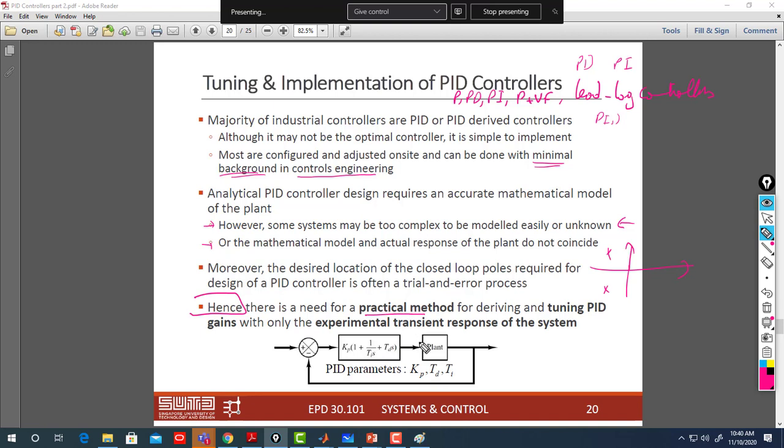But if you have a self-balanced robot and you don't think about getting the measurements, maybe it becomes difficult in this case. So think about having a Bluetooth link that transfers data from your self-balanced robot to your PC, and then you get the output of your response. This is very helpful to tune your parameters.